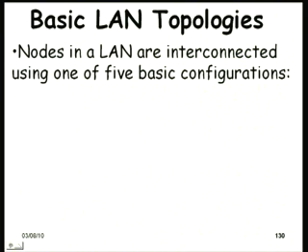Is that okay? Okay. This may cause starvation and all, like not starvation, what do you call? Undue delay for some, is it? Yes, see, the way the components are designed in an automotive application or any other embedded application where time matters, these are designed conservatively, taking the peak load into account, and normally it won't happen that a source never gets an opportunity to transmit. What might happen is it gets delayed, and the lowest priority messages, messages such as logging and so on, even if delayed by some time, it does not matter. But there may be some critical thing also, because it is a real time application.